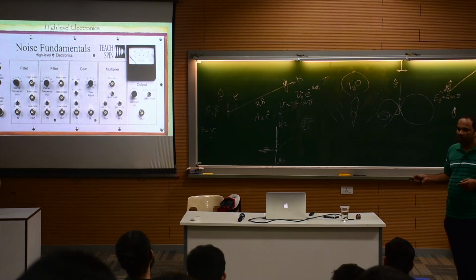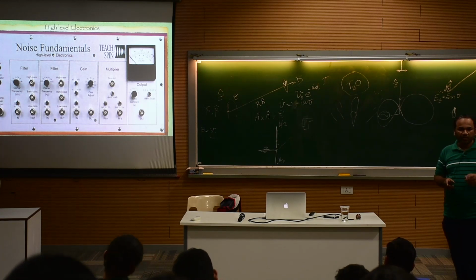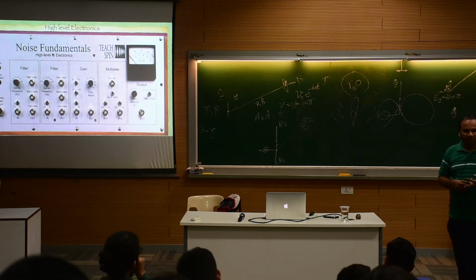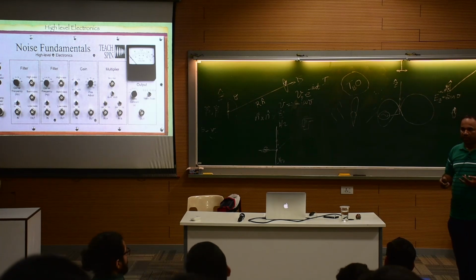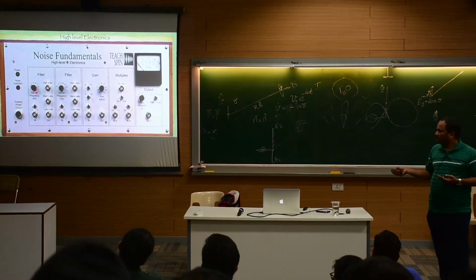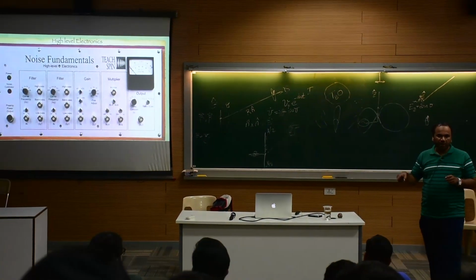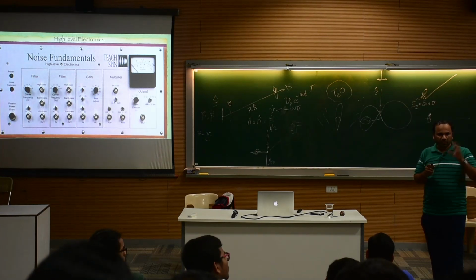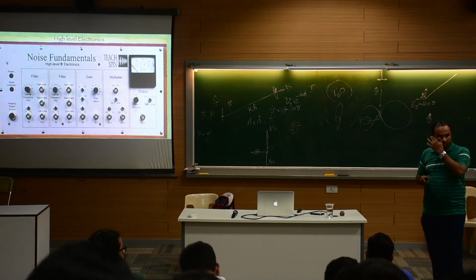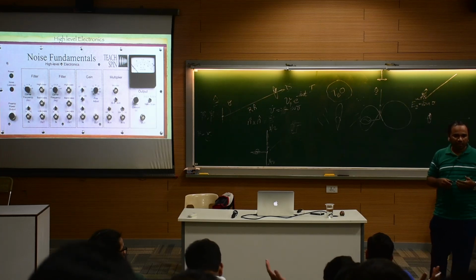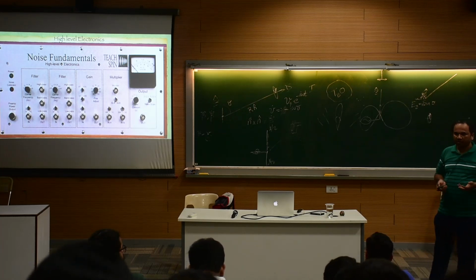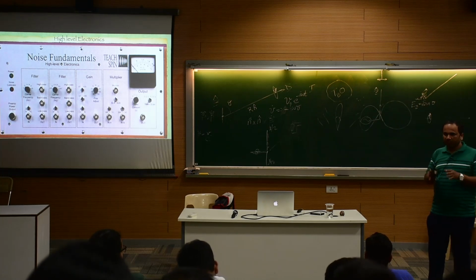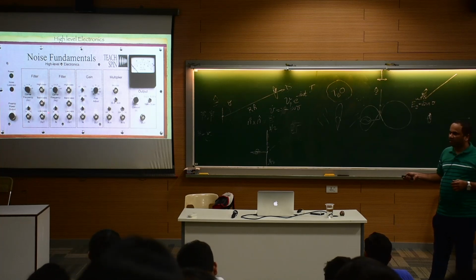So this is the high level electronics where we have two filters. To make a band pass filter, we need two filters: one is a high pass filter and one is a low pass filter. First we need to connect the high pass, and then the low pass, then it will form the band pass filter. What if we change it? First we connect the low pass and then the high pass, what will happen? It will act as a band stop filter. It will stop those frequencies and allow the other frequencies. So first we need to connect the high pass filter, then the low pass.